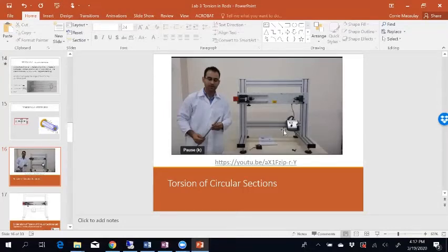Yep. So when you do the incremental force, the torque, is that just the force times the length of the rod that you're doing? No, not the length of the rod, right? So the torque, basically, if you think about a wrench and you're trying to turn a nut on your tire, it's that force that you put in, but you're going to multiply that by wherever your hand is on the wrench all the way back to the nut.